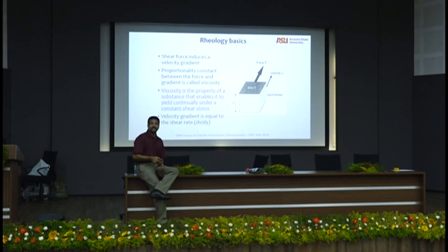But realistically, when it is sliding, which layer will have the highest velocity? The layer on the top will have the highest velocity. For the layer on the bottom, for theoretical purposes, you can assume that there is a very thin boundary layer that stays constant, stays without moving. It slightly moves, but generally you can say that compared to the velocity of the top layer, the velocity of the bottom layer is much lower.